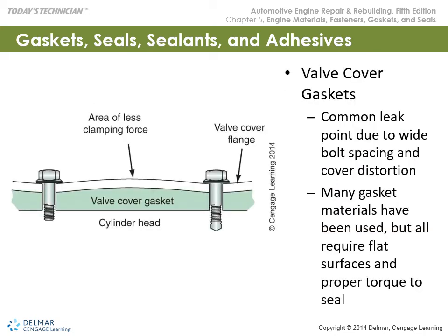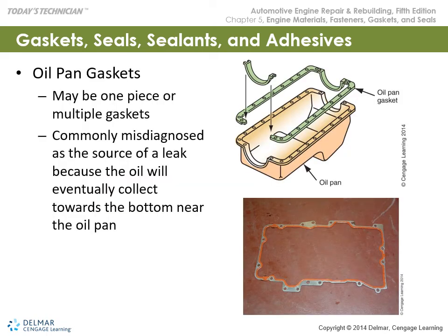Okay, here we're showing valve cover gaskets. Common leak point due to wide bolt spacing and cover distortion. Everything heats up. Okay, gasket materials are used, but we require flat surfaces and proper torque specifications and torque pattern. Okay, same thing with oil pans. We have temperature. We got heat from the engine block, and we're showing a half round gasket going into the pan, and we're showing they may or may not specify any sealant.